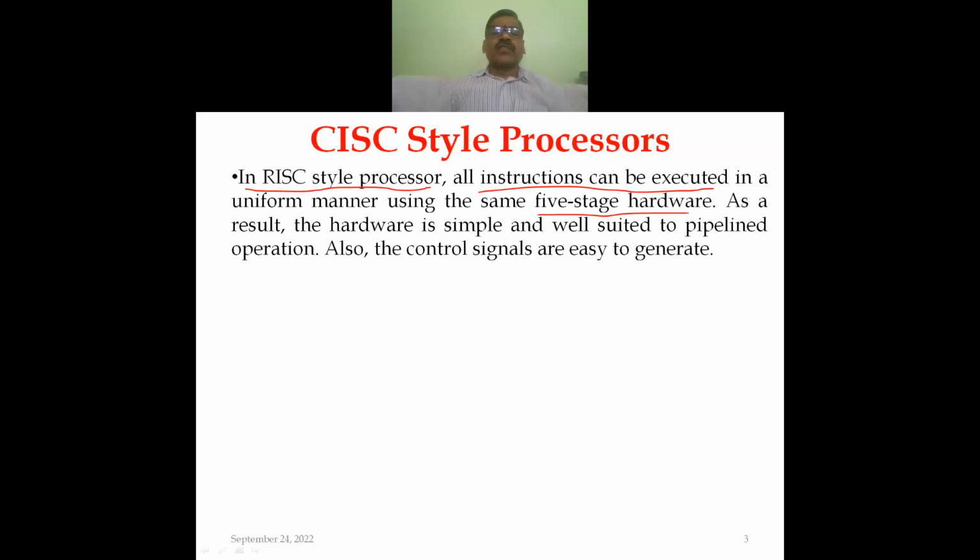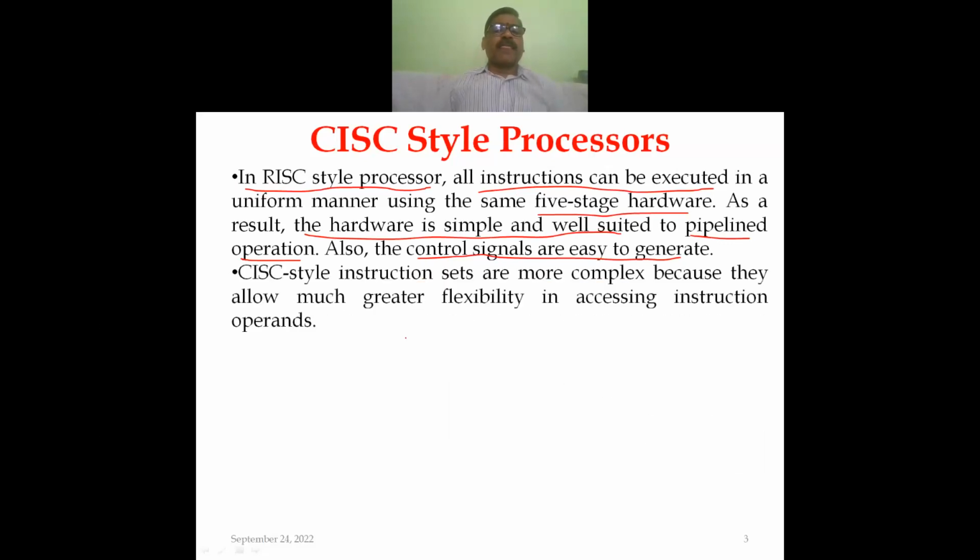As a result, we get hardware which is simple and well suited to pipelined execution of the instructions. Also, the control signals are easy to generate because we follow the same 5-stage hardware for any type of instruction in RISC style processors.